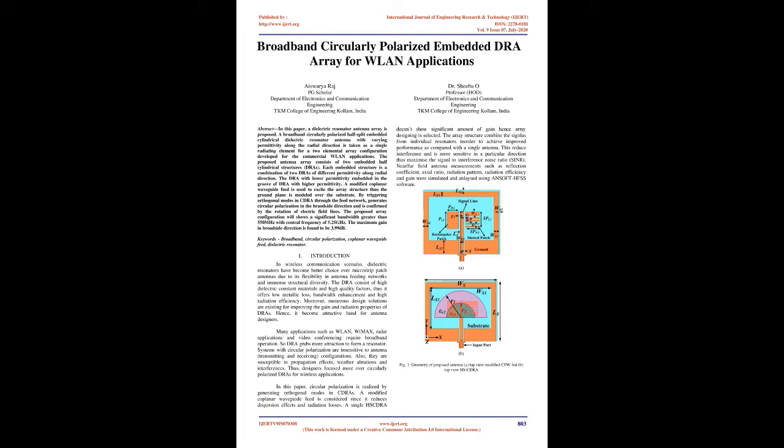A modified coplanar waveguide feed is used to excite the array structure, thus the ground plane is modeled over the substrate. Triggering orthogonal modes in the CDRA through the feed network generates circular polarization in the broadside direction, and this is confirmed by the rotation of electric field lines.